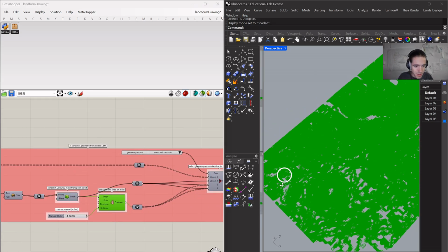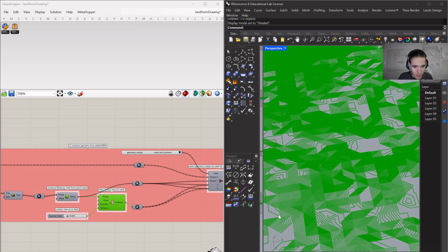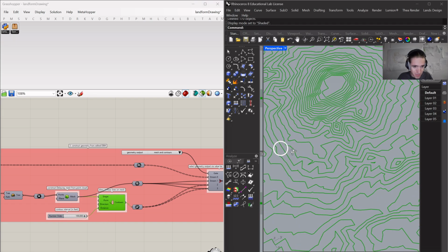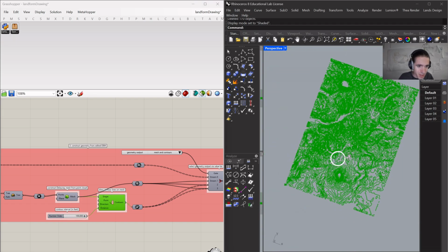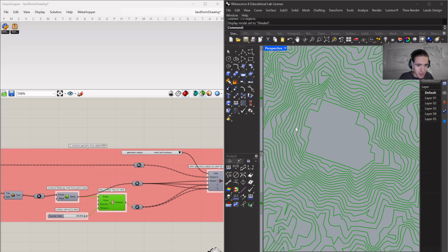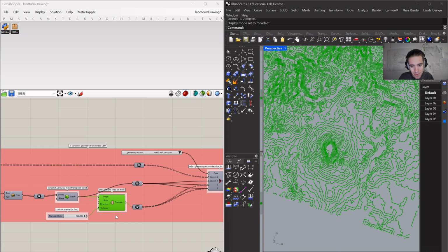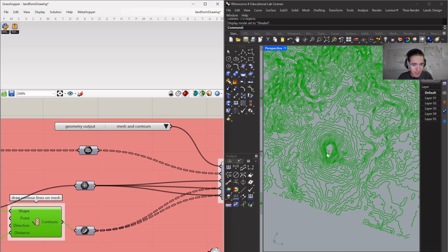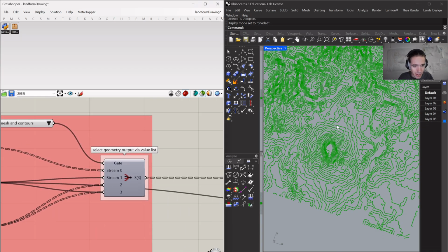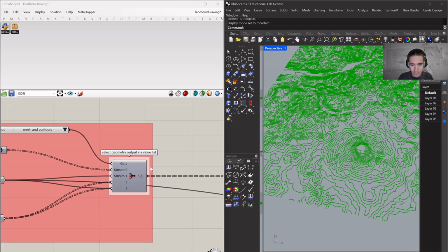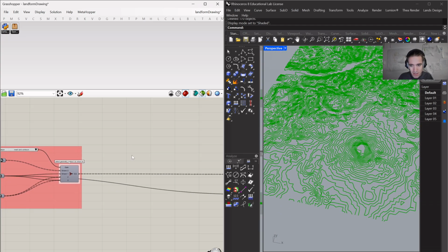We can look at our contours. Oof, those are 10-foot contours. We cannot do 10-foot contours on Mount Rainier. We can probably do 100-foot contours, and it'll still give us quite a few. But you can see you have one peak here. You have one peak here. These really need to be smoothed after you get them out of Grasshopper, but I leave that to you. Different people like to smooth them in different ways.